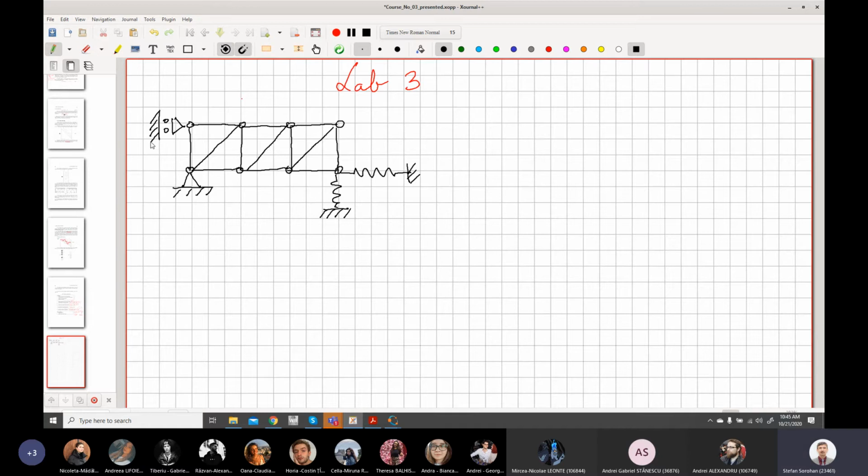point. I will consider, for example, in this point here, a non-zero displacement. Let's put node number 1 here, node 2, node 3, node 4, node 5, node 6, node 7, and node 8. So I have a total number of nodes of 8. And here I will take V8 equal to, let's say, 0.5 millimeters. So this point is enforced to have a vertical displacement which is not 0. Okay? And this point is enforced in the opposite direction of the y-axis.